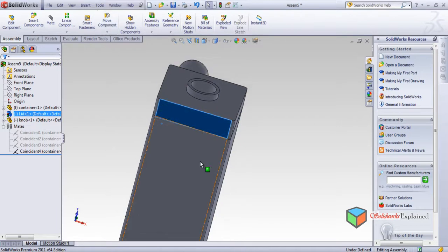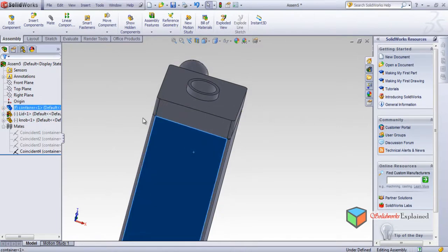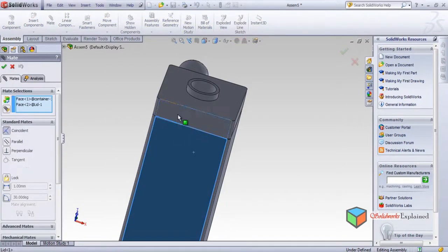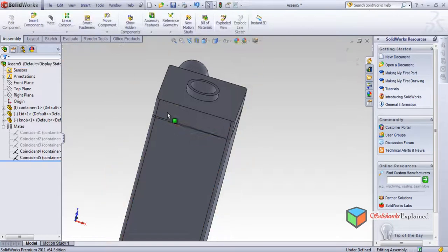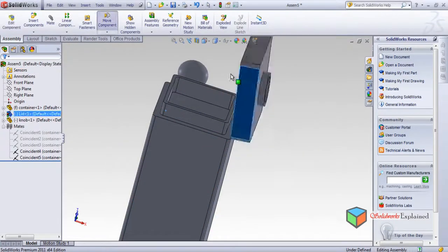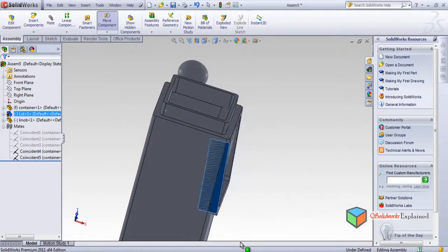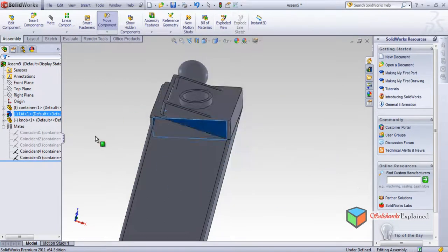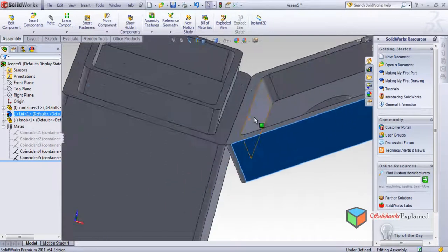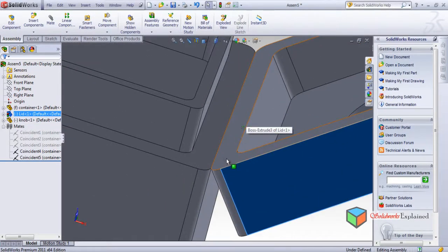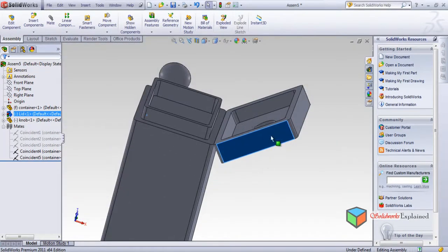So in this case, when you fix this thing, coincident this mate, you know, with this coincident and mate, look how it moves. Like a hinge it moves. You understand? Like a hinge it moves. But we don't want this motion, but somehow sometimes we'll need this motion, and it fits like this.